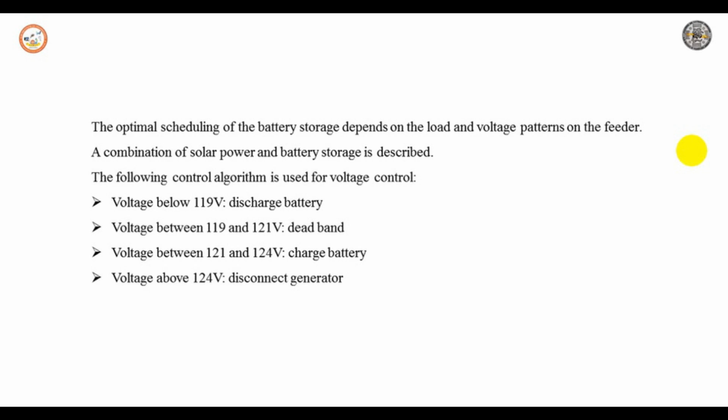So STATCOM is combined with energy storage. In their paper they have presented that fast voltage fluctuations can be handled and a more constant production maintained over long time scales. A local energy storage can be used to keep this voltage profile within its limit. The calculations referring to this study have shown that a few percent change in the voltage profile along this medium voltage feeder would require between a few hundred kilowatts to a few megawatts.